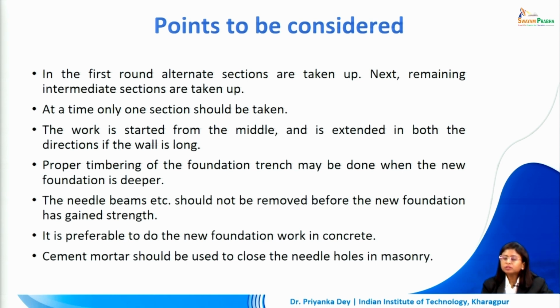It is preferable to do the new foundation work in concrete. Now cement mortar should be used to close the needle holes in the masonry. Definitely after the construction work is done, underpinning is done, we remove these needles, there will definitely be holes in the walls at the plinth level. So that is not something we want to leave. We definitely want to cover that up with appropriate usage of cement mortar.